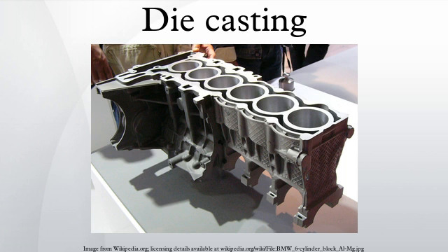Finally, the shakeout involves separating the scrap, which includes the gate, runners, sprues and flash, from the shot. This is often done using a special trim die in a power press or hydraulic press. Other methods of shaking out include sawing and grinding. A less labor-intensive method is to tumble shots if gates are thin and easily broken. Separation of gates from finished parts must follow. This scrap is recycled by remelting it. The yield is approximately 67%.